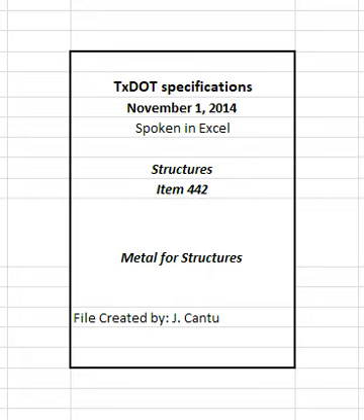2.1.3.4 Slip-resistant deck plates. Furnish steel for deck plates that meets ASTM A786 and one of A242, A588, or A709 GR50W. State the type and trade name of material to be used on the shop drawings.